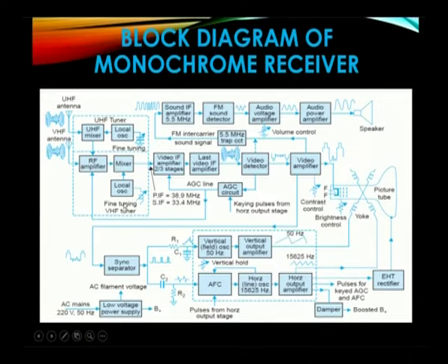In the mixer we need to tune for a particular channel, right? That has to be done from the local oscillator in the receiver part, which is set manually. By selecting a different frequency, we can discuss this part in detail in upcoming slides. The local oscillator gives the tuning for a particular frequency, and this is sent to the mixer. In the mixer there is some subtraction that happens. So we get a signal, and that signal is sent to the video intermediate frequency amplifier.